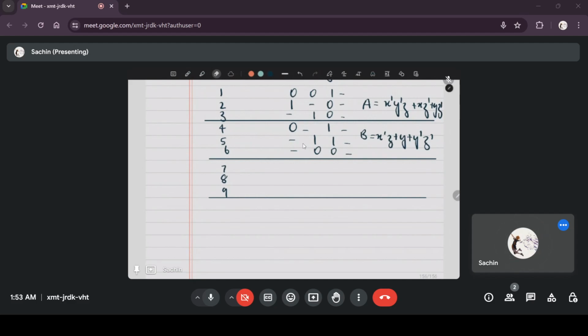So three terms in the sense you can have up to three product terms. You're provided three AND gates for each of the output functions and one OR gate. So you can have three product terms and then OR them together. But you don't need three product terms for C because C is simply a plus xy. So you can just take a and xy, and D is just z plus x bar y.